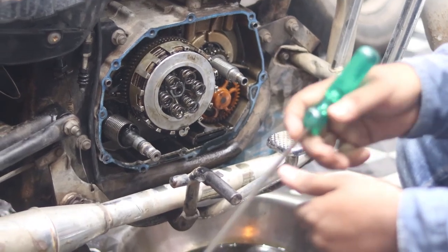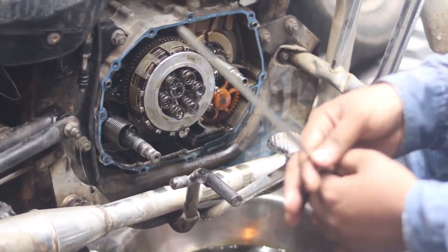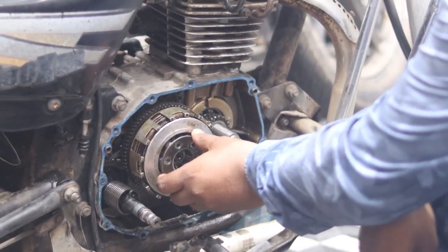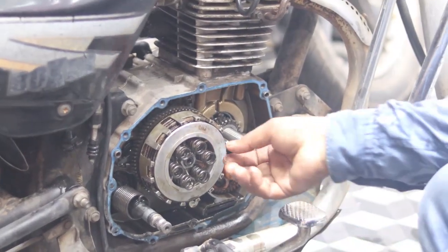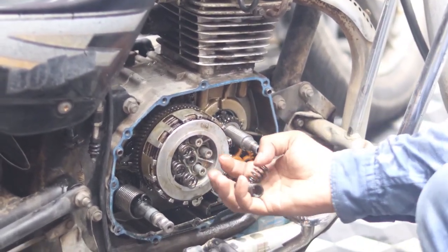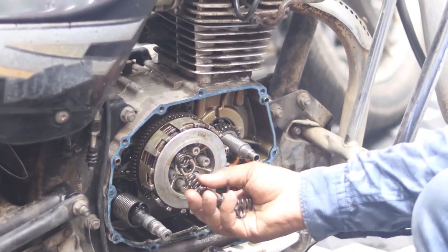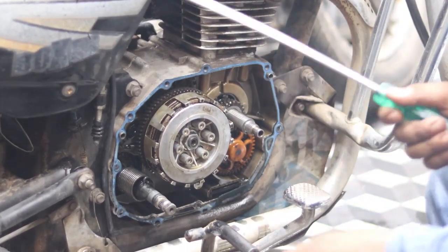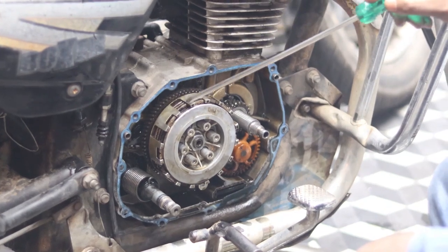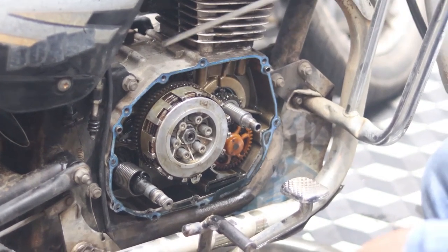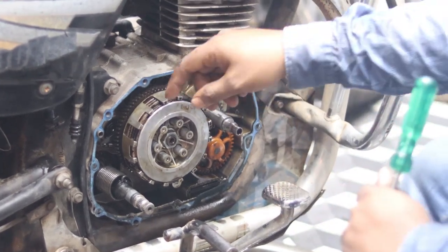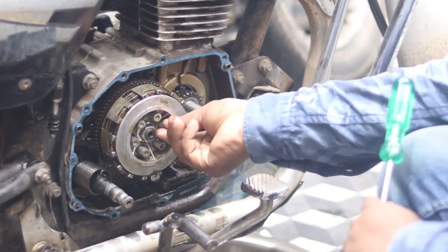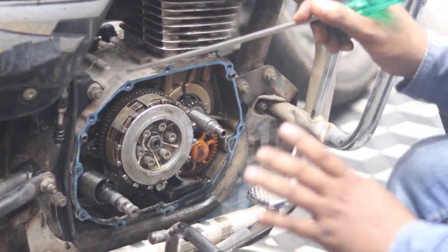Now we have unbolted the whole clutch system. Here there is a plate used above the spring, and we have removed it. After this, the springs are used, a total of 6 springs are used here. And then here is the pressure plate, and the clutch plate mountings are here. On the outside you have seen these splines, this is called the clutch plate, and inside it there are a number of pressure plates. So you have seen this assembly is the mounting of the different types of clutch plate and pressure plate.